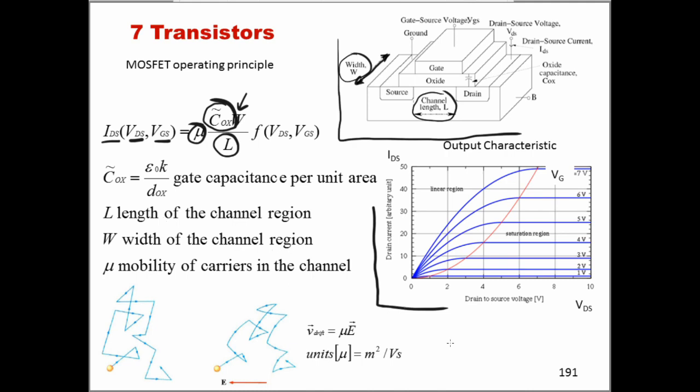And so by recalling that the charge in the channel is COX times Vg, we can quickly realize that for every given value of Vg, the larger the capacitance of the gate stack, the larger will be the charge in the channel, and so the better our transistor will behave and the more current it will be able to deliver.